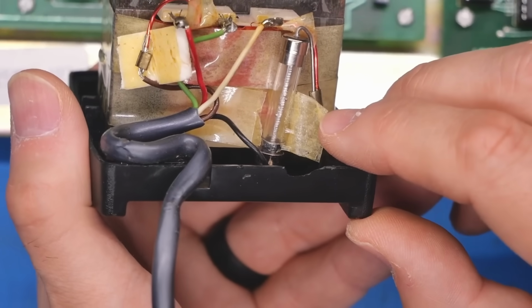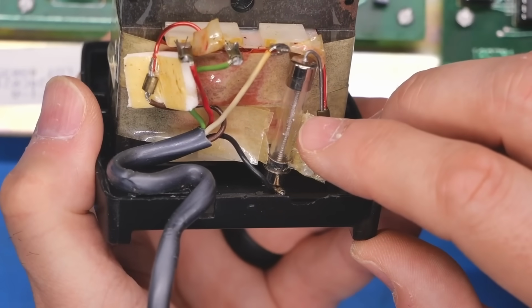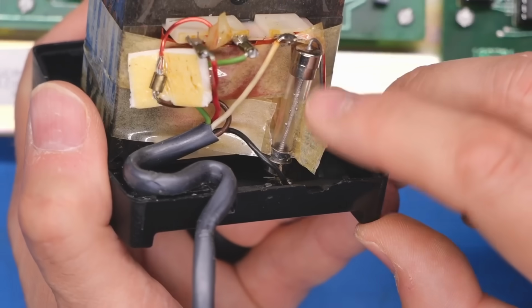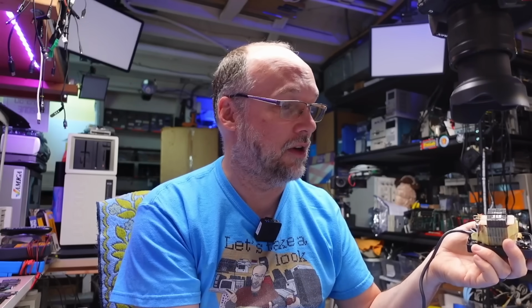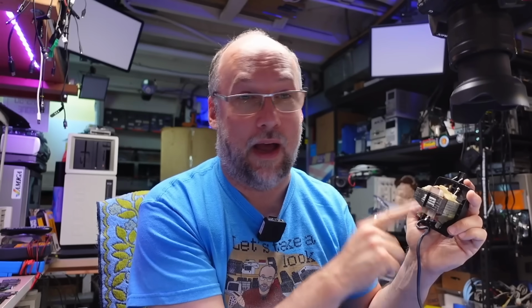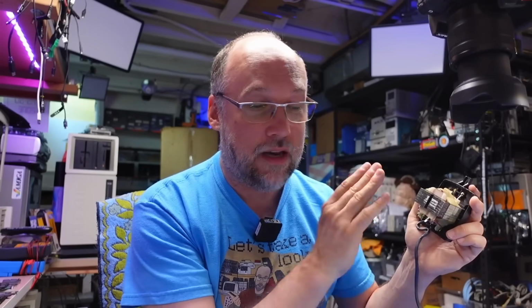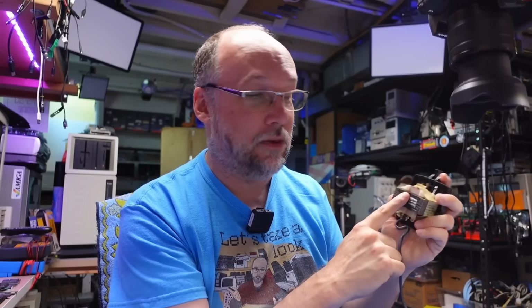Now I did cut away the tape so we could look at the fuse, but you can see the little solder balls on there, and I definitely confirmed this is open. So my hunch this had a fuse was right, and I'm glad I went through the effort to open this thing up, even though it was kind of a destructive process. But I think I should be able to get that fuse replaced. And then what we can do is we can measure the voltages of this power supply, so that if you get one of these and it doesn't have the original power supply, I will at least have documented the way that this power supply works, so that you could potentially recreate it yourself.